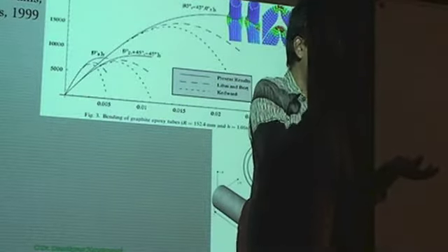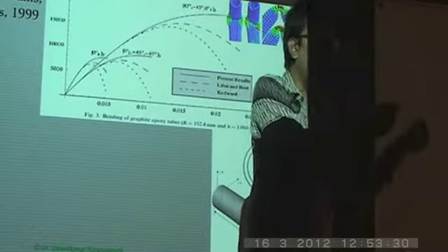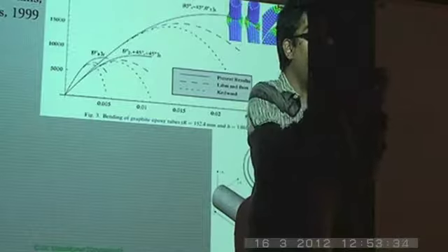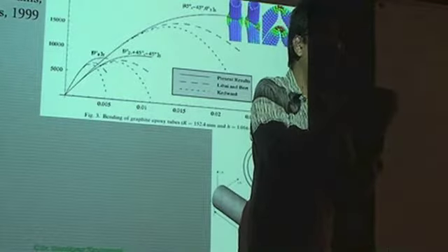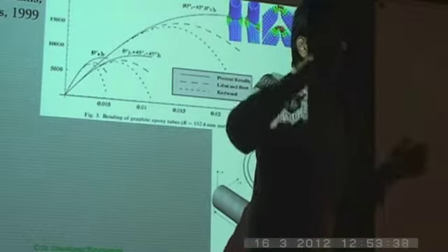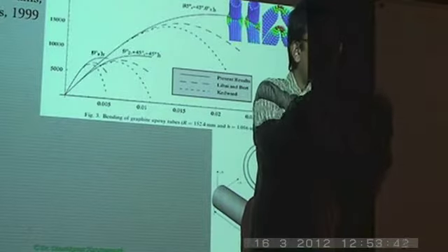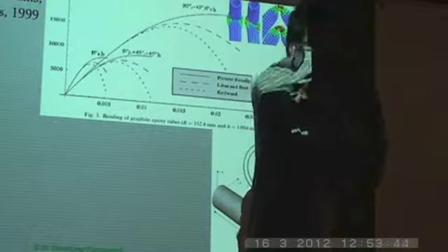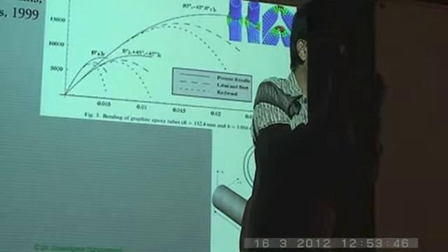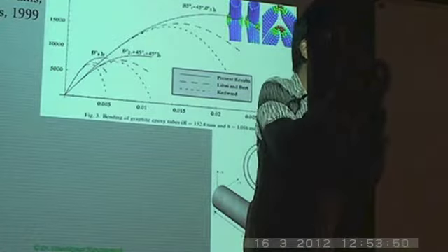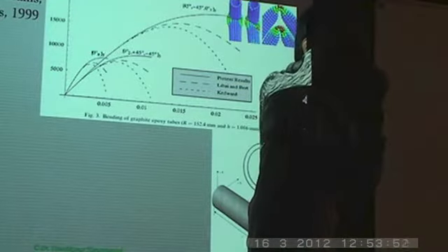See, even material failure is a local problem. It starts off at a particular location where the stress is so severe that basically the material at that location fails, and then of course it spreads, the damage can grow. But basically it's a local phenomenon. Similarly, your local instability is because of a particular location where the compressive stresses are large and the geometry is such that, because it's thin wall, remember, it can have a local kink which is taking place.